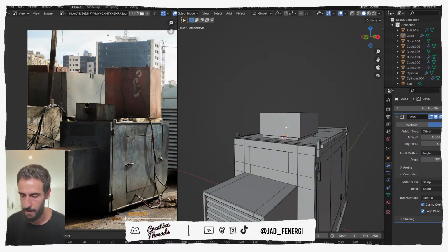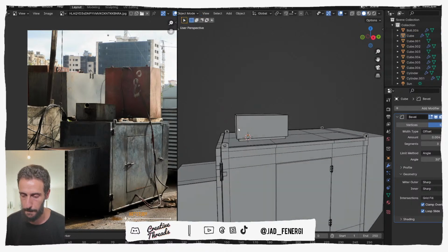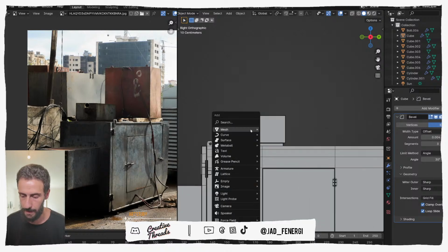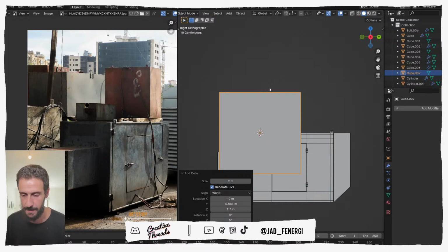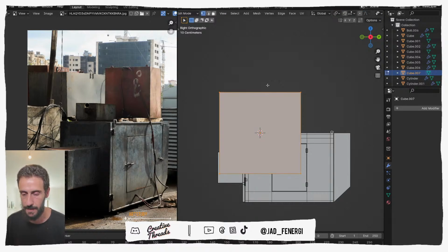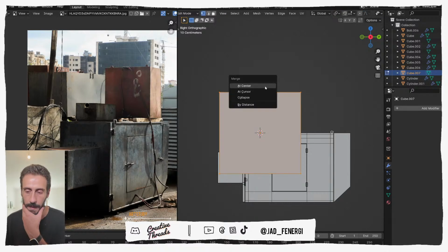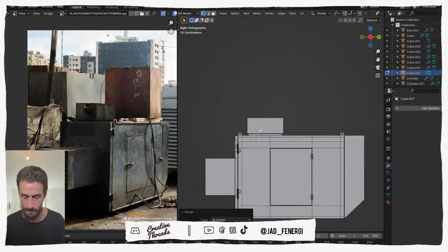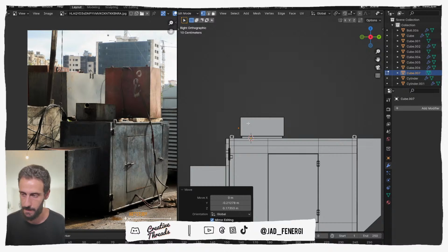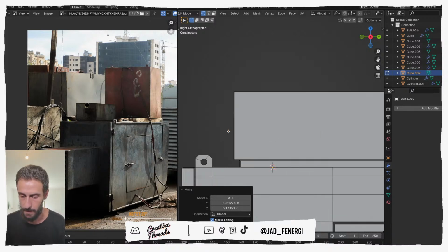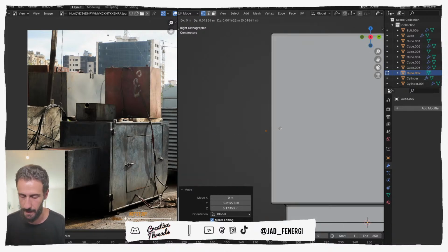Yeah. All right, so what we can do is create a cube. You can press Tab in vertices, select everything, press M, and merge everything at the center. So what we end up with is just a vertex, okay? Then there are different ways to do what I'm showing you, but this is one of the ways.